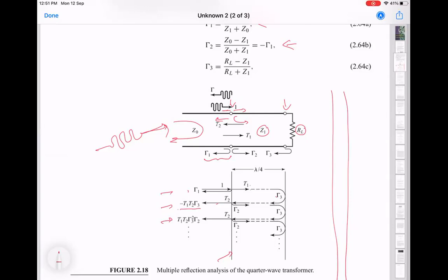In some sense, it will take infinite time to become truly zero. But since we are not usually worried about something being exactly zero here anyway, this is not incompatible with the frequency domain picture as well. Because a pulse, any signal which starts at some point of time, is not a fixed frequency signal. So remember, impedance matching happens exactly at one frequency.